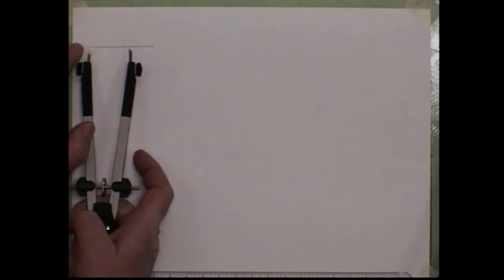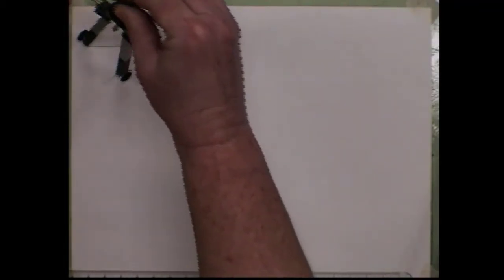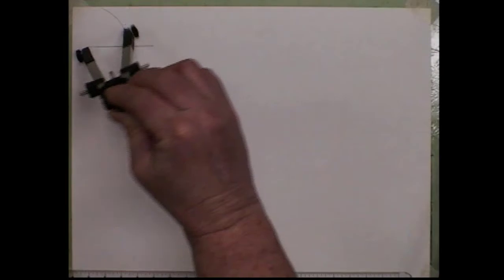You're going to have to follow along, so make sure you're staying focused. So needle point on one side, wheel the compass out. We're not putting any kind of measurements or anything. We're not using our scale at all. But once you get it wheeled out past the halfway mark, then you're going to put the compass at the end point and strike an arc. So you can strike it all the way like a half of a circle here.